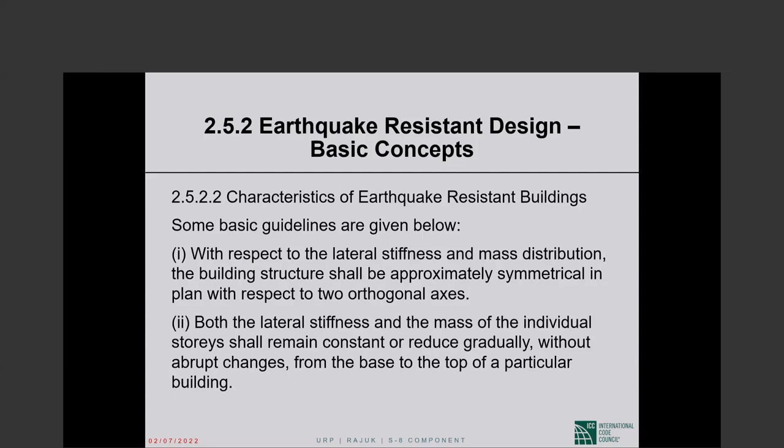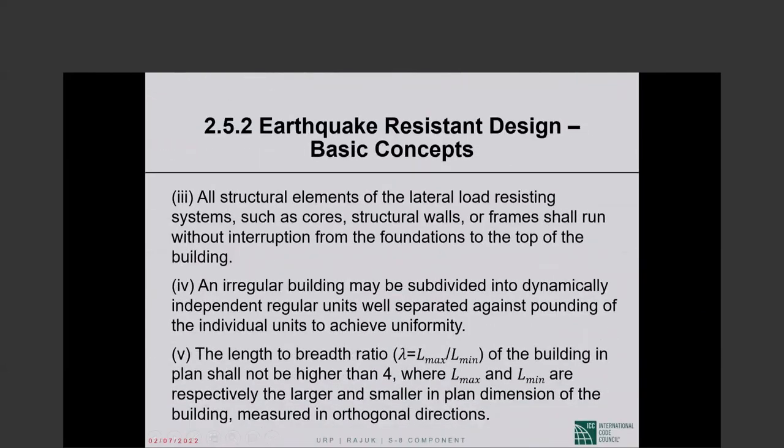Quite a few things are said. Decrease gradually without abrupt changes. You go to a place like Dubai, you will see all the buildings violate all these principles. Okay, the buildings have larger plan as you go up, so instead of reducing gradually, things increase. Anyway, all I'm trying to say is real life is different from the principles that are given here, but the principles are nonetheless good. Definitely, that's what you should aim for.